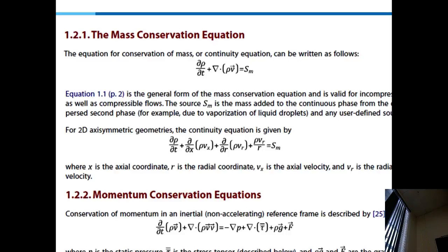So there is no phi dependence. This is different from expanding that equation in a Cartesian frame. Most of these solvers have both options: solving in a Cartesian frame for any complicated geometry, and for those that have the axisymmetry property, solving this set of equations. That's why you need to check that box to pick this set of equations to solve an axisymmetric problem. So that is the continuity equation with a source term.